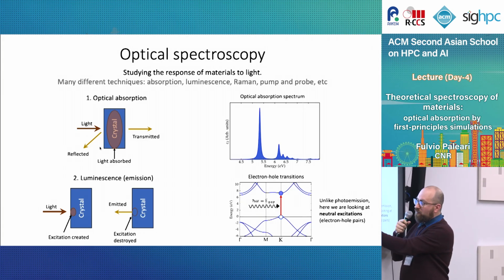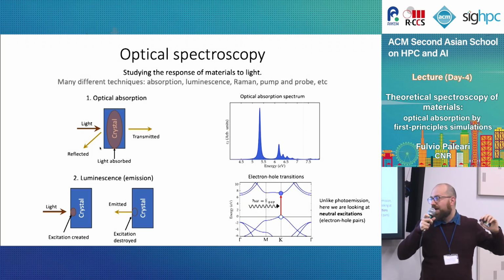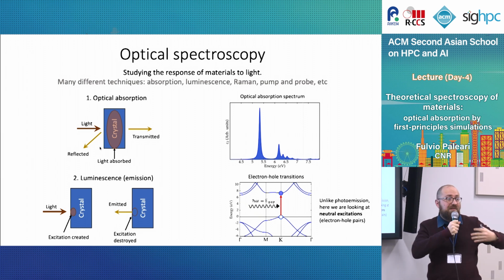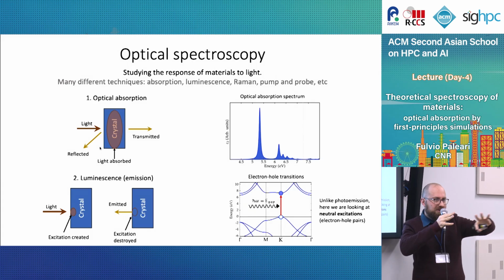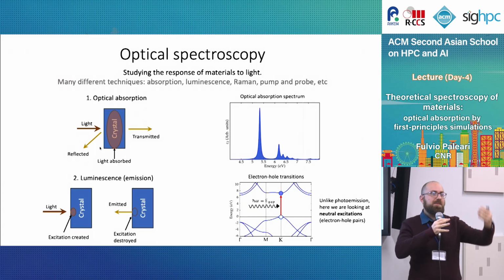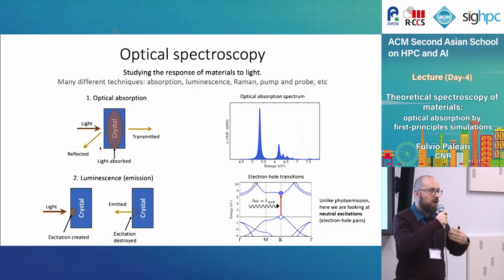And so the electron goes here and leaves behind, let's say, a vacancy where it used to be before, that has an effective positive charge. Imagine that you have an organization of electrons in your system, then one electron moves, what remains there with respect to the ground state is a kind of effective positive charge. And this we call usually the hole.